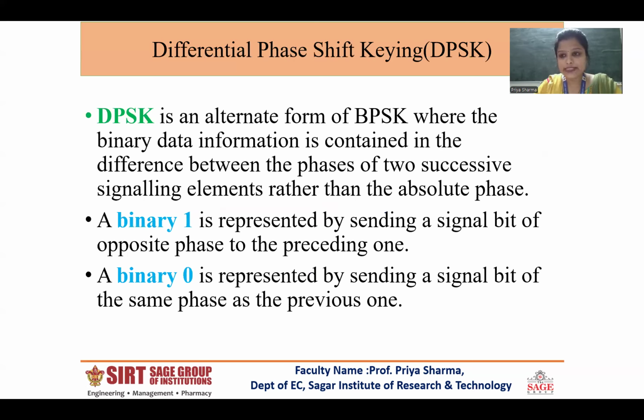Coming to the DPSK signal, it is similar to what we read earlier, not in this lecture, but earlier in PCM. It is similar to DPCM. DPCM and DPSK are similar. There, we send the difference between the pulse samples, the amplitude sample difference is sent. Here also the phase difference pulse is sent.